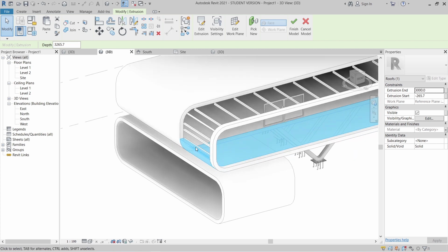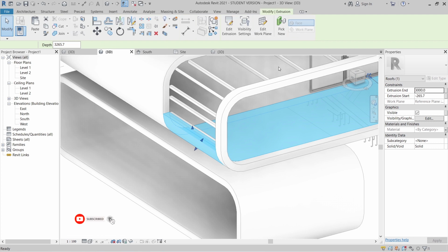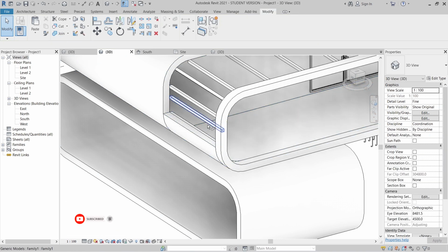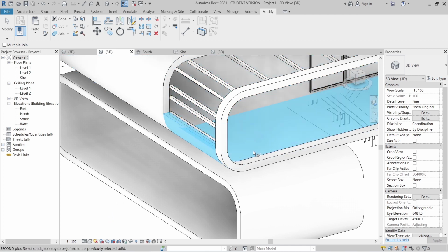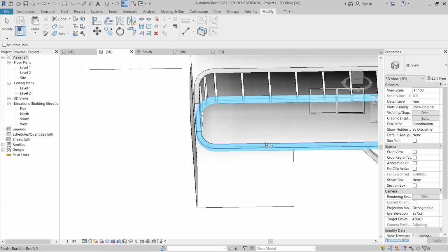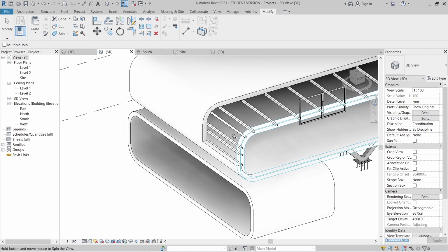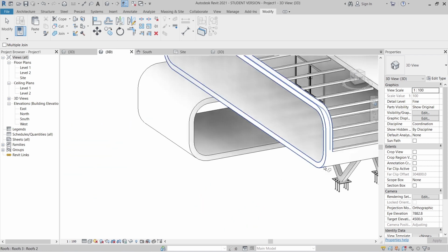Okay, as you can see, it's perfect. What we need to do next, I'm going to join elements. We just hit finish first. Only then you can join. Go to join element, join from our inside to our floor here, and join from our floor to here. Okay, let me see first. Is everything perfect? Let's join all.